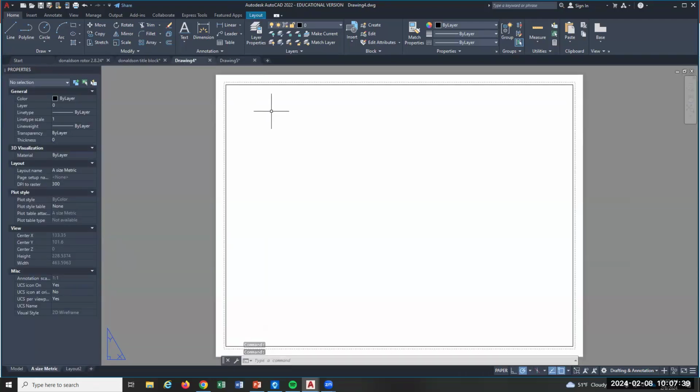Good. All right. So it's not impossible. Like, you'll forget. You'll just open AutoCAD, and you'll start drawing thinking you're in metric. You'll get a couple hours in and then realize, oh crap, this thing's huge compared to what it should be. Metric, it's going to be small, right? You can scale things. You can make them bigger or smaller with the scale command. Now, it doesn't switch it to metric, but it does switch it to the correct size.